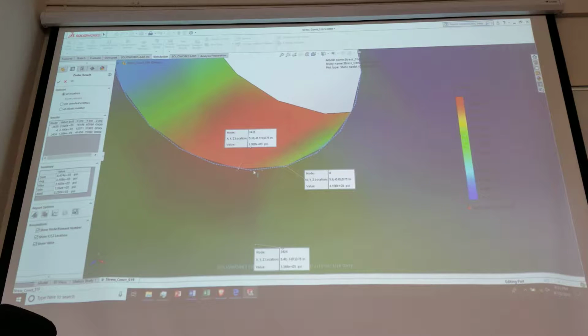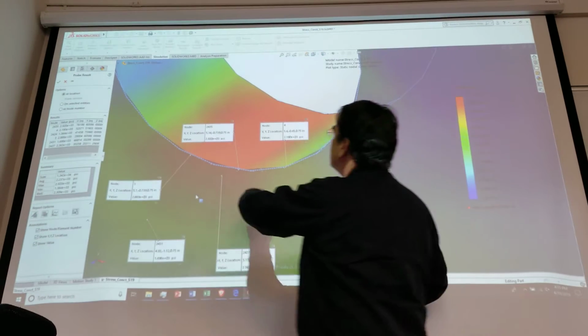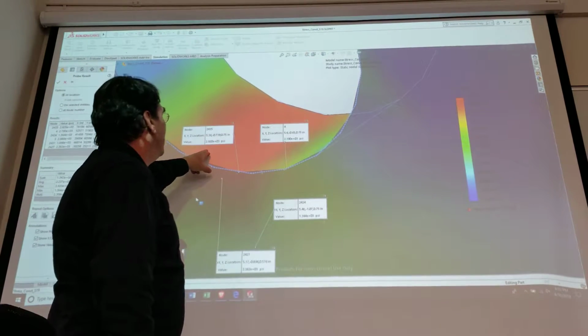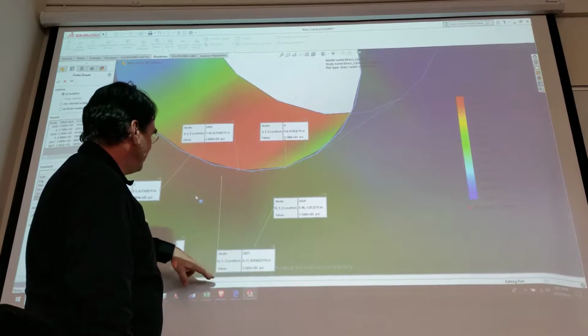And I'm even worse if I go down here. And there's nowhere in between here I can click because there are no nodes in there, right? The next node's over here. It's 20, at least these two are pretty close to each other. But then if I go down in here a ways, they're dropping off really significantly, and there's nothing in here I can click to because there's no nodes, right? So there's a huge stress gradient. I mean, we go from this area here, which has about 3 KSI, and then we're dropping all the way off.